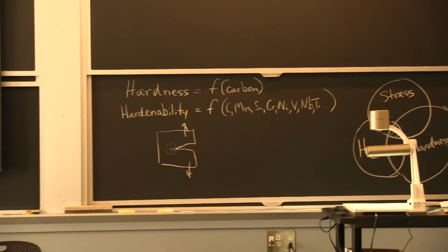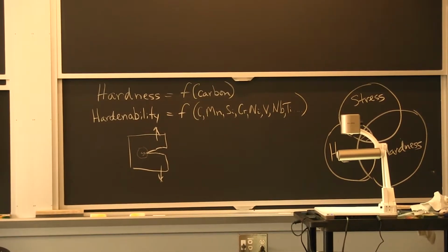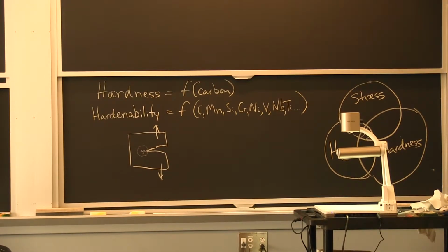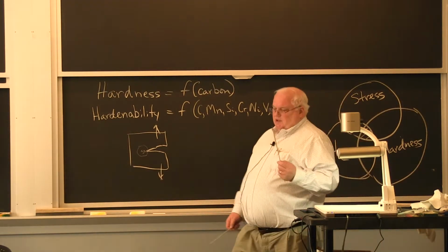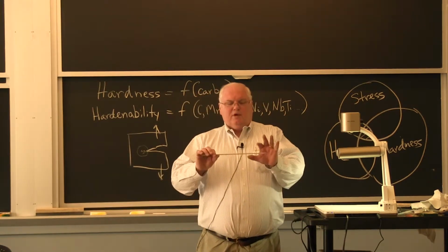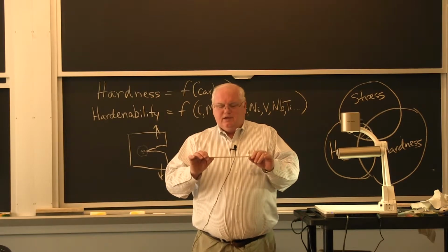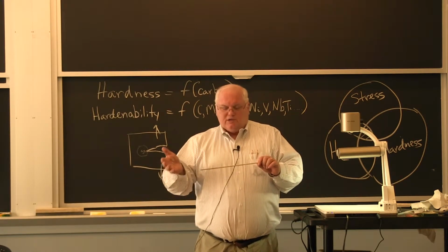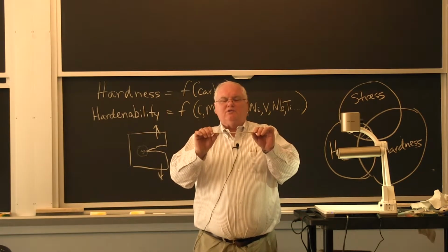Actually, I'll keep 2 of them, plus 2 others. So here's 3 different types of welding electrodes. There are dozens of types of steel electrodes for different steels. The 6011s, the 60 means 60 KSI strength. The 11 is the type of coating and the type of polarity, AC, DC positive or DC negative from your power source.